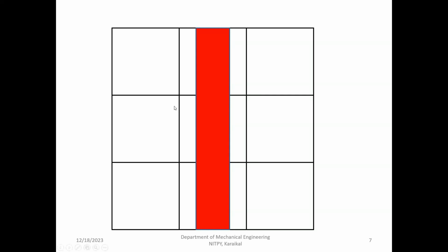So if you take this particular cell, the energy coming in of the fuel and oxidizer is going to be converted into heat, and then exhaust gases will be taking some amount of energy. So energy coming in is going to be equal to the energy going out. But in finite difference, the temperature here may be around 30 degrees Celsius, but here it may be around 1000 degrees Celsius, or around 900 degrees Celsius. That's possible. So this strong difference in pressure or temperature we can manage in finite volume much more easily than in finite difference.